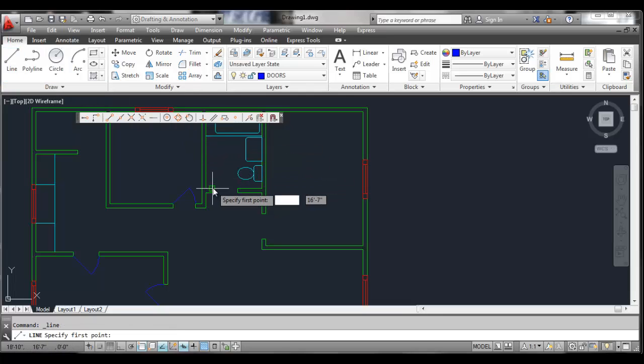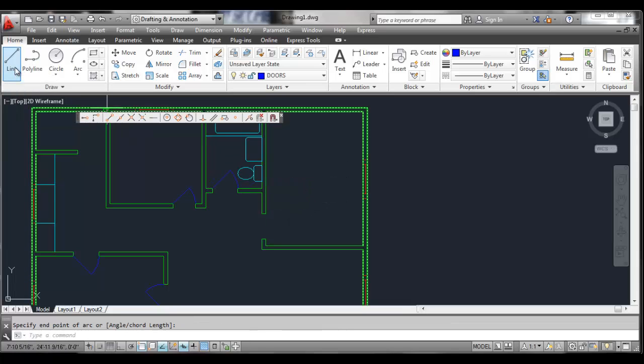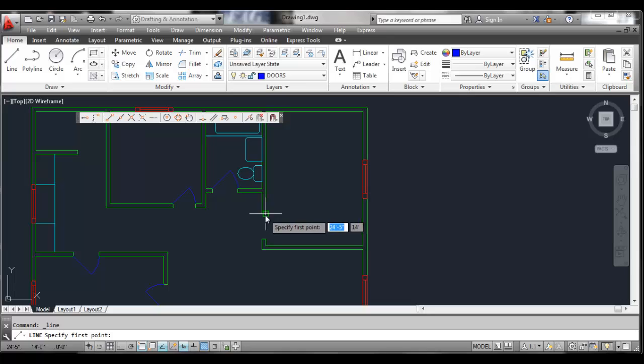And the next one is right here. And this one is 2 feet 8, angle 45. And create the arc, start point, center, and end point. And another one right here, 2 feet 8, and negative 45. And then the arc, start point, center, and end point.